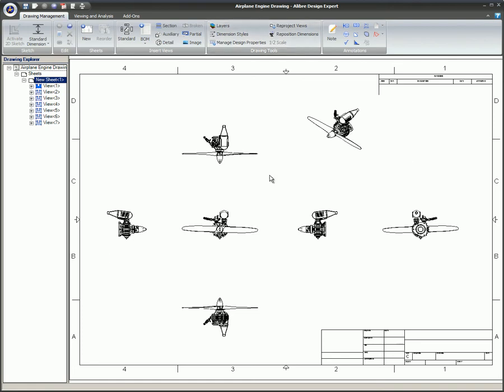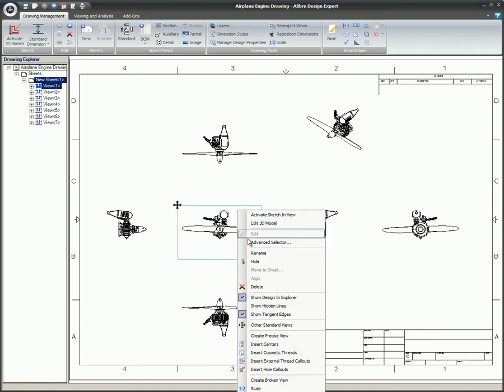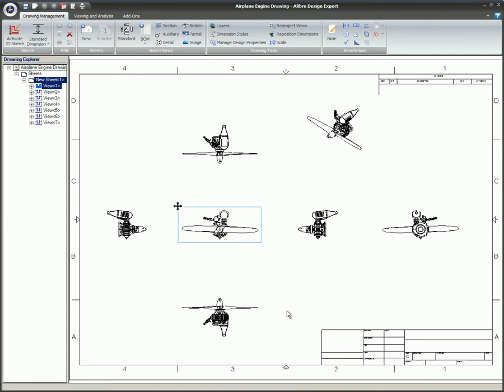Reprojecting views. If only particular views need to be converted from fast to precise, right-click on the view in question and select Project as Precise. This will not update the view based upon the model, but will simply change the view type. So if the model has been changed, those changes will not be reflected in the view that is being updated.